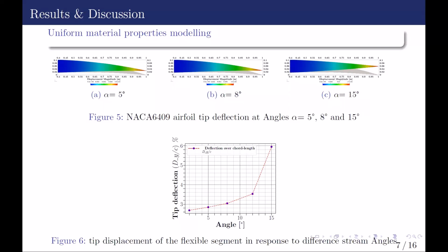If you ask why, it's because we are mimicking the bird's wing, where about 40% is bone and muscle, and we don't have much information about what material properties we can implement in that part. So we are confident about the 60% in which we can implement the feather properties such as Young's modulus and some bending stiffness characteristics that we have from experimental biology.